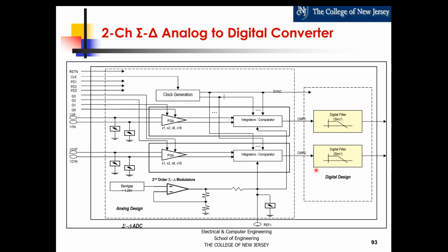That is the frequency response of the sinc function. So to make it more prominent, we cube that and raise it to the third power. So this is a decimation digital filter that implements the transfer function cubic sinc.